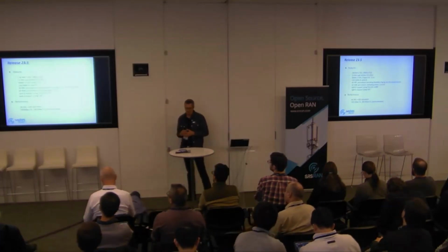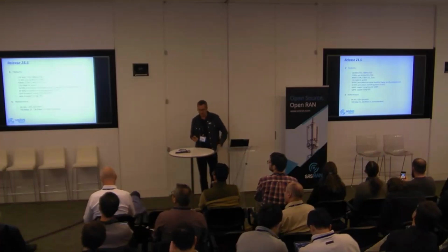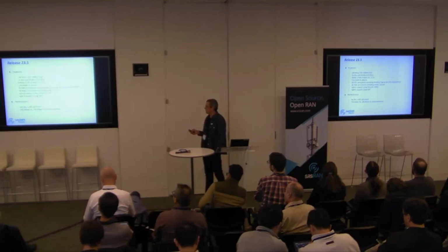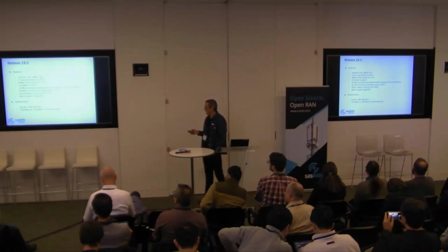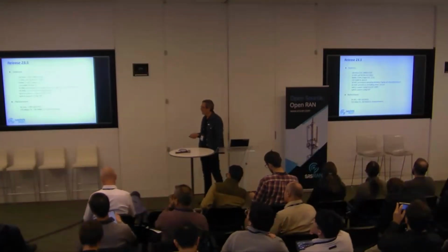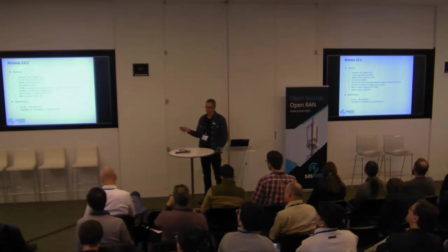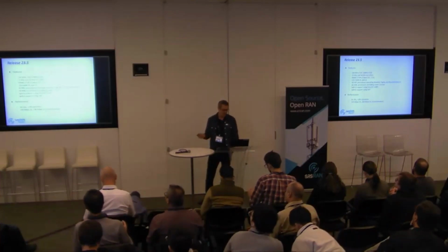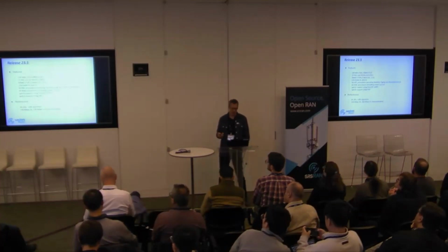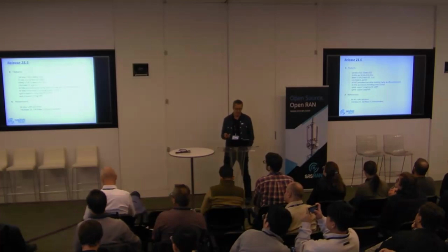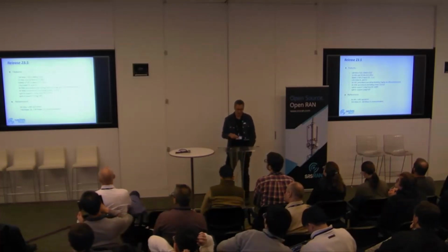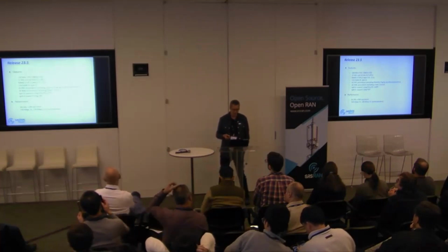So this was the initial release of the code after being 1 year silent. The code could already do 100 TDD or 50 FDD, and it was achieving a performance of 700 megabits per second in the downlink and 100 in the uplink. This obviously depends on the TDD pattern. We were already supporting 15 and 30 kilohertz, and it was doing MIMO 2x2 in the downlink, 1 layer only in the uplink. 256 QAM in both uplink and downlink.